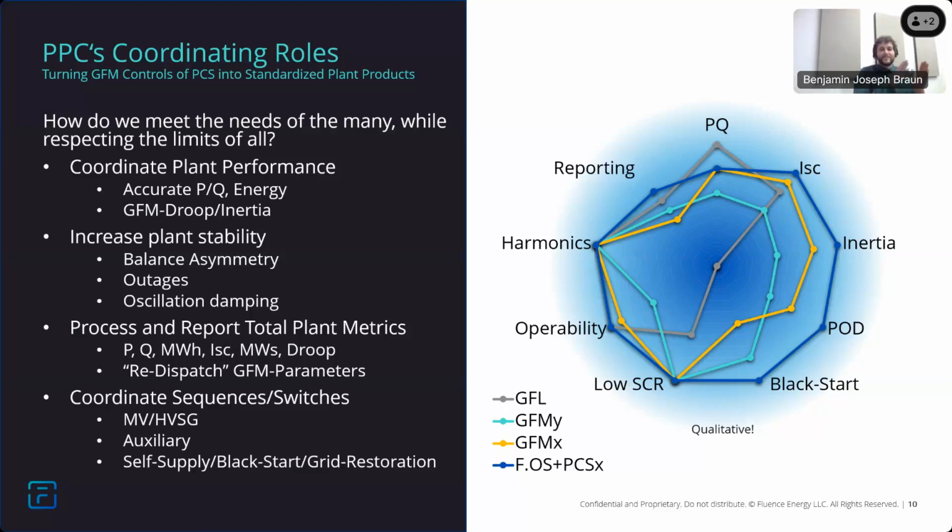As I said, you have a paradigm shift from the current control to the voltage control. In the current control, the PPC tells an inverter to do something and it does it. And it tells another inverter to do something and it does it. And it does that across its entire plant, and everything can be balanced and managed from the central controller very conveniently. Moving to a voltage source with grid forming controls, suddenly the PPC has to manage much more dynamic entities.